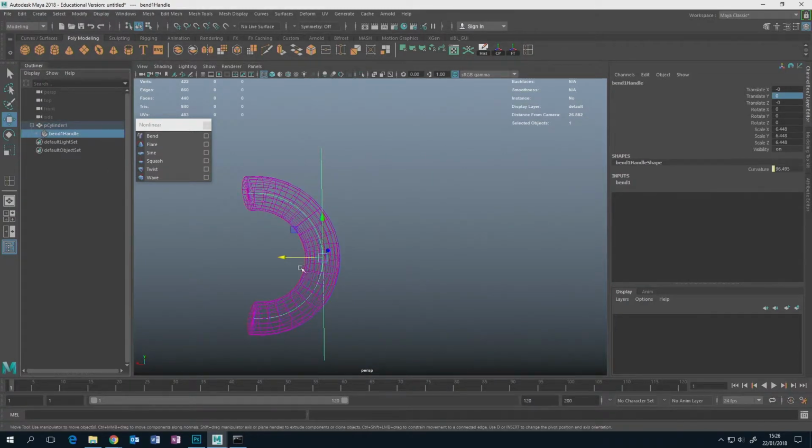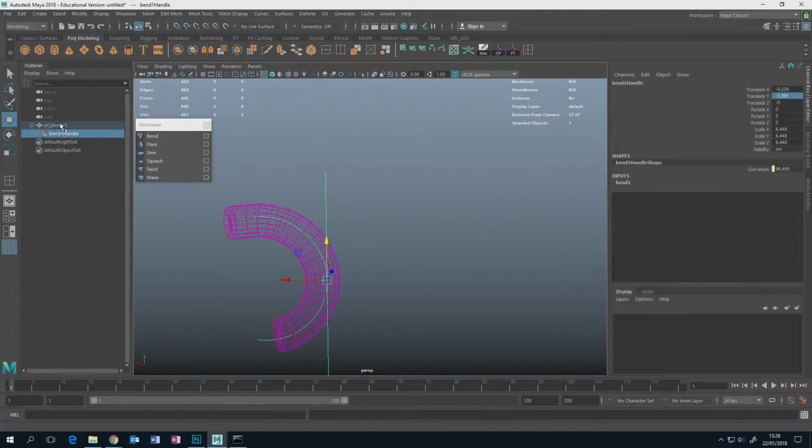It means that you can do an overall deformation on an object, but then you can still go in and make fine-tuned little edits to your object by extruding, beveling, or whatever like that. And your deformer, because it's not really connected to any of these components, will still apply that deformation to the overall object. And Maya comes with a whole bunch.